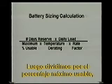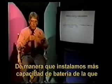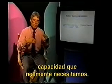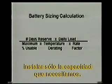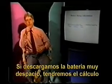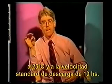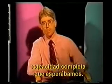Then we divide by the maximum percent usable. We also divide by the temperature derating so that we install more battery capacity than we need at 25 degrees, so that when the battery is extremely cold, it will have the capacity we really need. And we also divide by the rate factor, so that we install only the capacity that we need. If we discharge our battery at a very slow rate, we'll now have the calculation for the amount of battery capacity we need to buy at 25 degrees, and at a standard discharge rate of, let's say, the 10-hour rate. So that as we're slowly discharging our battery, we get the full capacity that we expected.